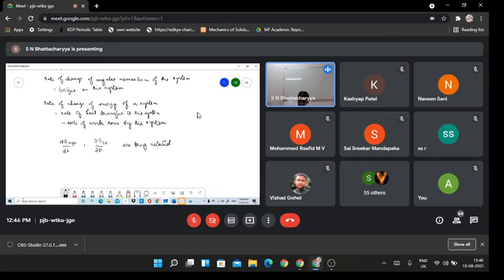At the moment, we just say it is a certain property which is an extensive property, associated with a specific property. The specific property is the property per unit mass. So if I have such a property, can I relate the rate of change for a system to the rate of change for a control volume? Then, if I have a relation between the two for a system, I can apply these laws.